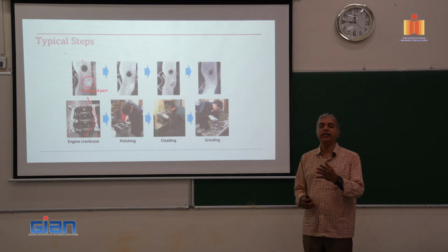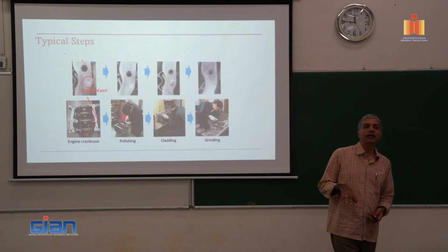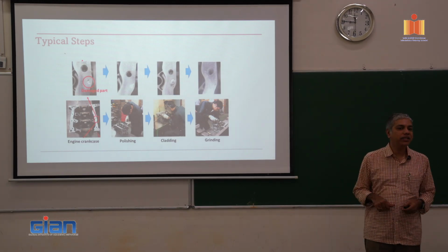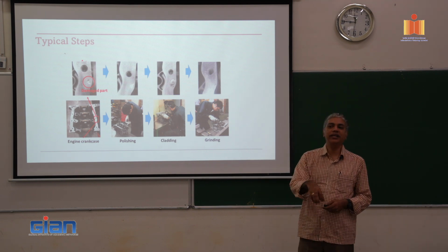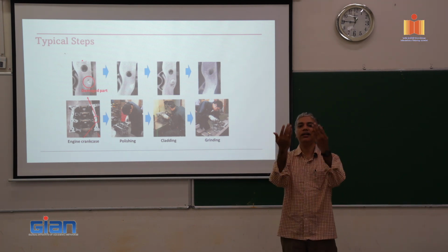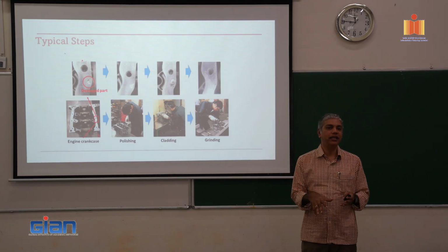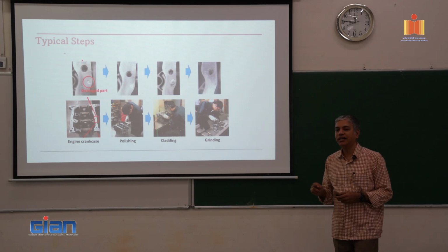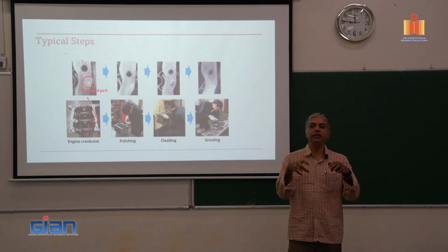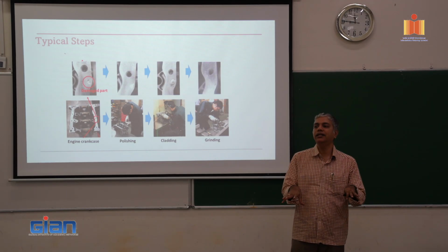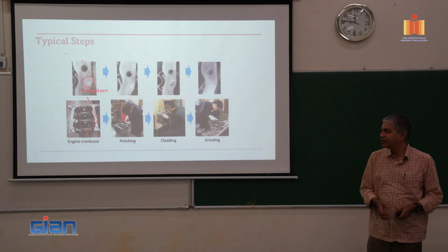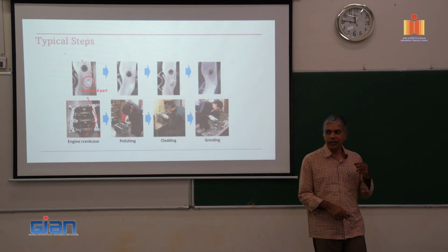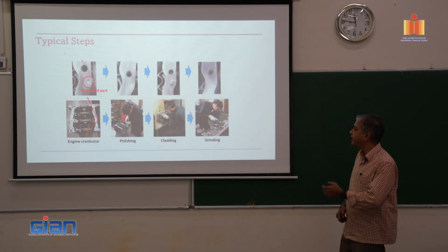Have you seen road repair done? Usually, if the rainy season comes and the roads are damaged, they don't just bring the tar and put it there. Why? Because the whole tar will just come off. There is enough dust, etc. So they consciously even sometimes damage the road further, so that whatever material is being added does not come off easily. So polishing, cleaning, etc. is part of the preparatory steps for repair.